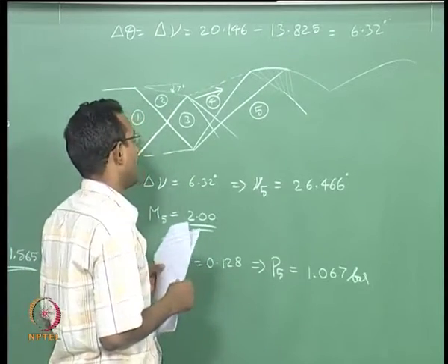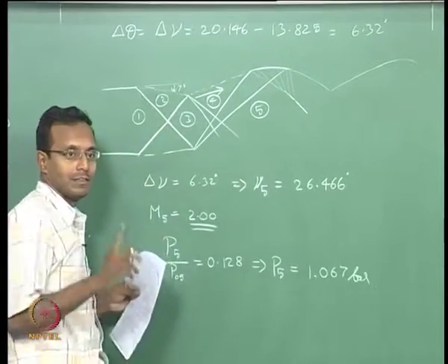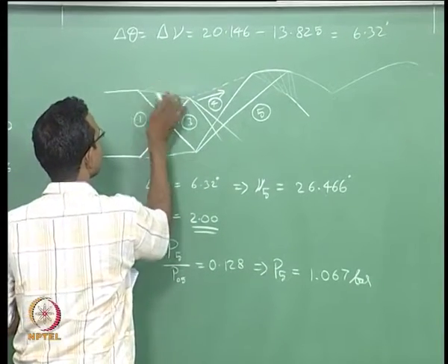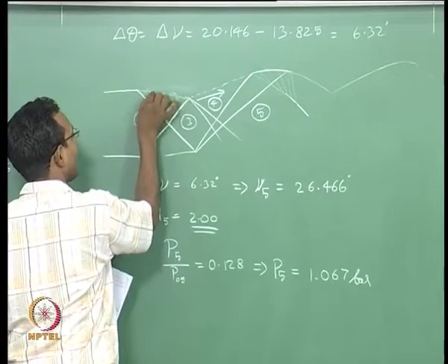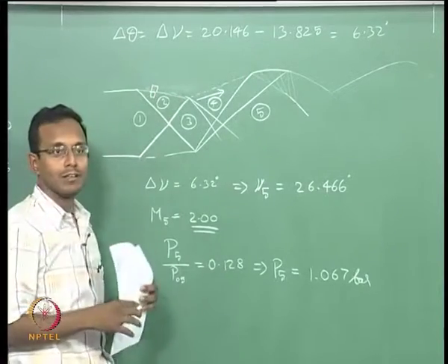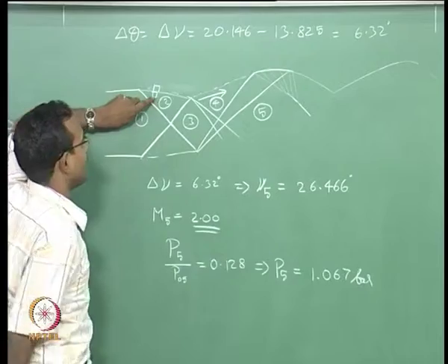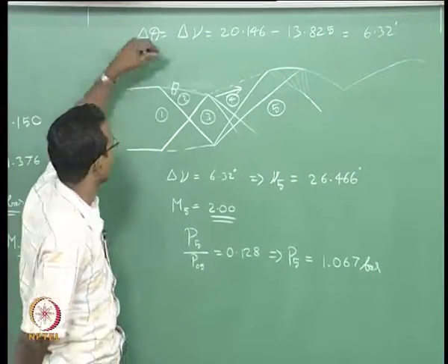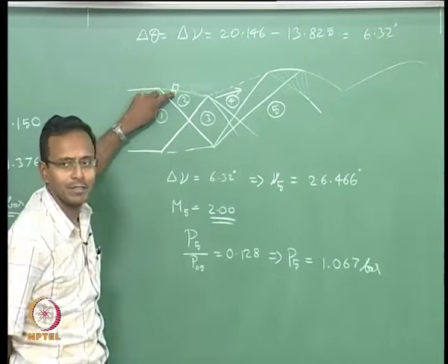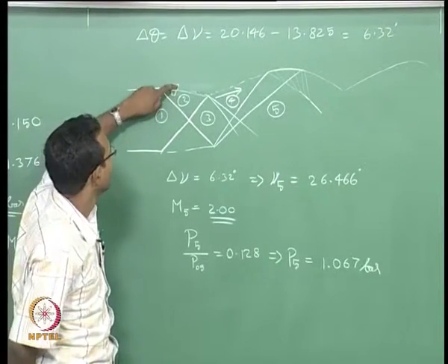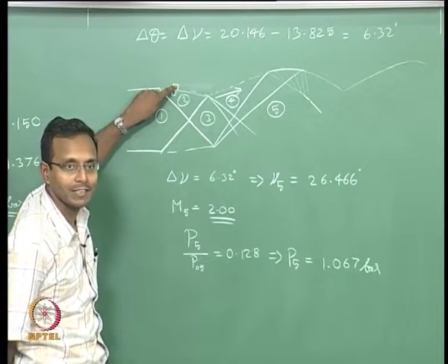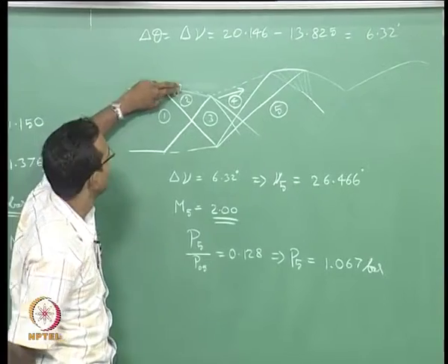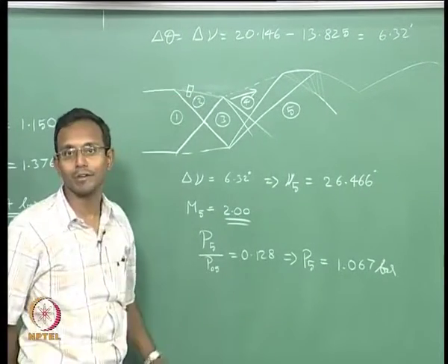But if I have viscosity present, then this particular line along which the fluid is going has a fluid element below and a fluid element above. We know that the fluid element at 2 is moving with whatever velocity corresponds to Mach number 2, some value. It will be pretty high, not very small, while the outside is supposed to be stagnant gas just sitting idle. If that is the case, there is going to be a very high velocity gradient at that point.